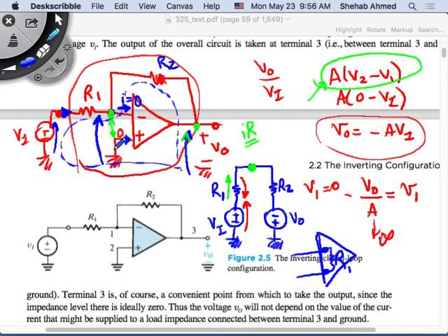What happens to the current? Where does it go? You tell me. So here is 0. Does it go back to the output? Yeah, exactly. That's how it gets its gain. That's where it's going to go. There is nowhere for the current to go besides up in this branch. So if it goes up this branch, then with current flowing in this direction, I have a voltage drop in the opposite direction. Yes, it's Kirchhoff voltage law.